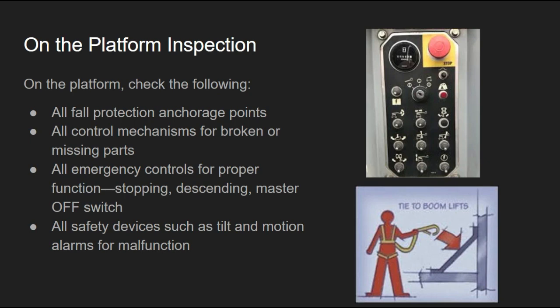All fall protection anchor points. All control mechanisms for broken or missing parts. Check all emergency controls for proper function: stopping, descending, master off switch. Check all safety devices, such as tilt and motion alarms, for malfunction.